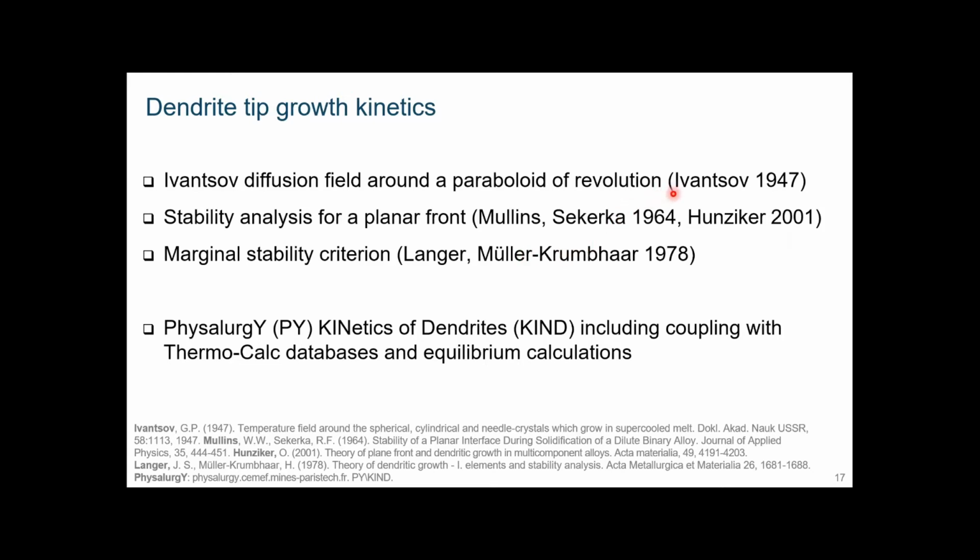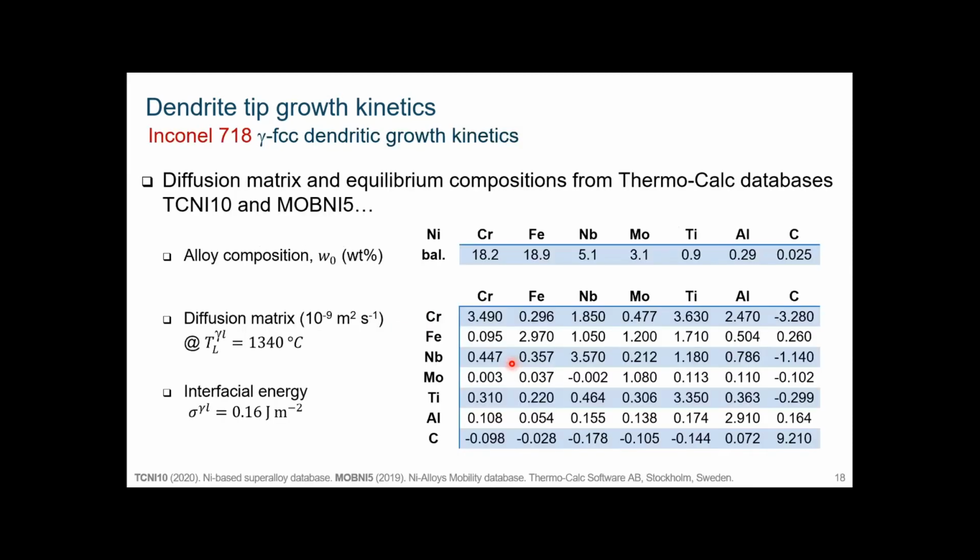Using all these theories, you can inject these equations into a code that calls Thermo-Calc databases to compute equilibrium and to access diffusion coefficients. This is what we did. We call this module coupled with Thermo-Calc. It's part of a library we have named PhysiOlogy, for physical metallurgy models, where we compute kinetics of dendrites. We apply that to the Inconel 718 alloy. This is the alloy composition. Some of you will recognize the composition.